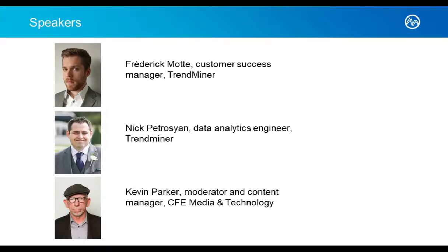And then we also have functionalities inside of TrendMiner to do aggregation. So for example, if you have a really noisy tag, or if you have some missing data, we have different functionalities in TrendMiner that you can use to smoothen out noise and things like that. And those are typically those quick wins, right? So during onboarding, we can focus on a couple of those quick wins that already save loads of time, because those type of filters can be reused over and over again, and you don't have to go through the same steps every time.